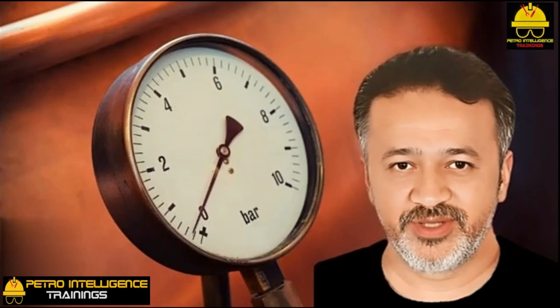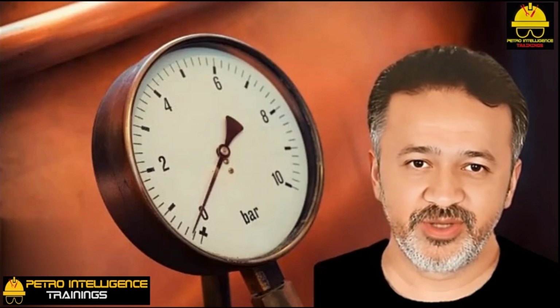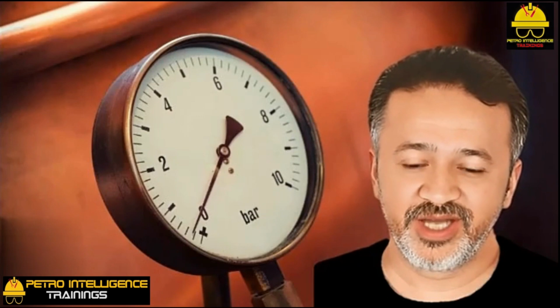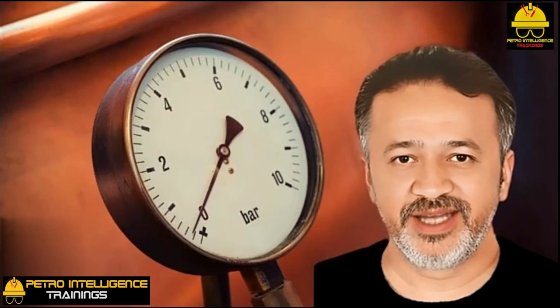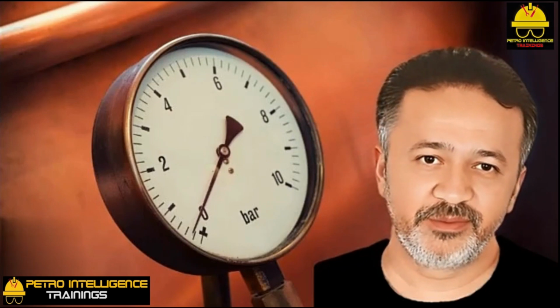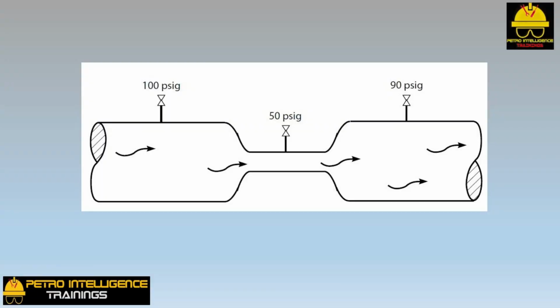The reason the orifice flanges are kept close to the orifice plate is that when the liquid velocity decreases downstream of the orifice plate, the pressure of the liquid goes partly back up. This picture illustrates this point. It is called pressure recovery. Whenever the velocity of a flowing fluid, vapor or liquid, decreases, its pressure goes partly back up. An extreme example of this is water hammer.